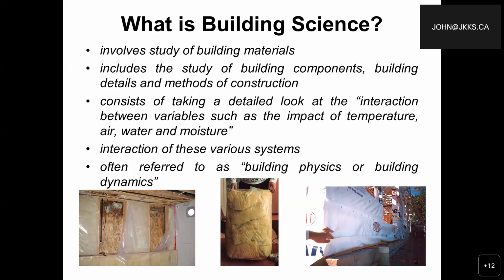The last image over on the right is me holding up a little bit of, we'll call it the wall covering, the air barrier. And if we take a look along that concrete block wall, which is a concrete block foundation wall, in the sill plate, we can see some shims because the foundation's out of level, but there are big, huge air gaps left there for air to leak inside the house. So again, all of these give us a little bit of background on why we look at things and why we need to look at it in detail.